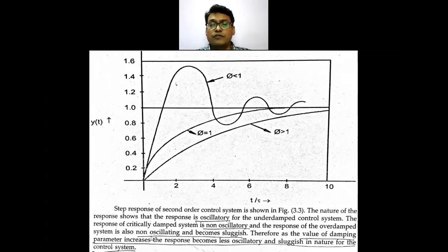So therefore, as the value of the damping parameter increases, the response becomes less oscillatory and sluggish in nature for the control system. This is most important.